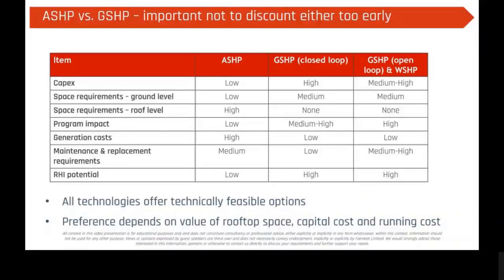The other one is technology. I'm not going to talk about this in loads of detail, but on most projects, this will come up in terms of, okay, we're doing a heat pump into a heat network. Are we doing air source, or ground source, or water source heat pump, or energy from waste feeding into a heat pump? Predominantly what we're seeing is air source heat pumps, and that's largely driven by the fact that air source heat pumps are the lowest cost pound per kilowatt compared to ground source and water source.